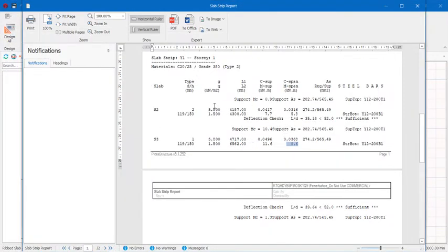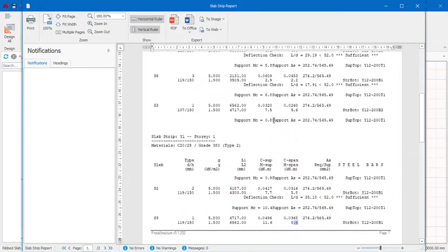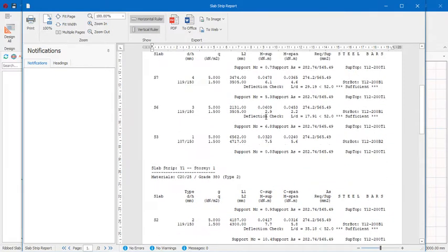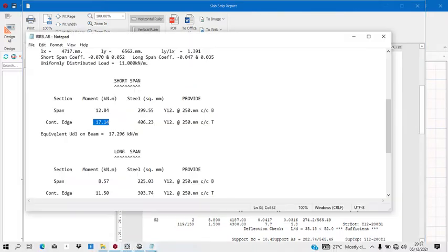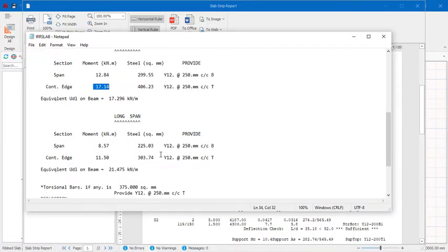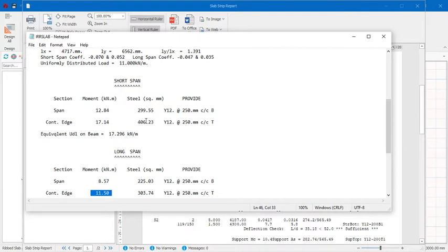Short span will now be X. It is saying 11 and 8, which is short of the moment I am supposed to have. And look at what it's saying for the long span, 7.5 and 5.6, which is also short of what I'm supposed to have, 11.8 and 11. So you can see this variation in the moment, and the moment is what is used to calculate the steel.